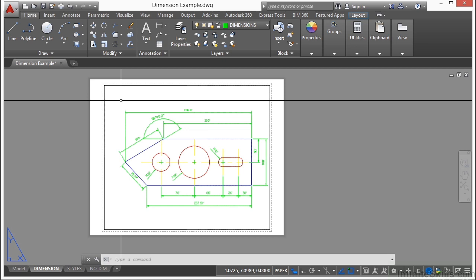After you finish arranging the layout, you turn off the layer oftentimes that contains the layout viewport objects. Alternatively, you can set the viewport layer to a no print setting, which is what I typically do, so that it's visible on the screen but it won't print out. In either case, the views are still visible, and you can plot the layout without displaying the viewport boundaries. Just to recap, Model Space contains the drawing geometry or the model, and Paper Space is what's going to be printed out on paper. That's the main difference between these two spaces.